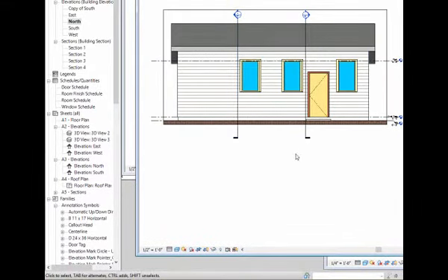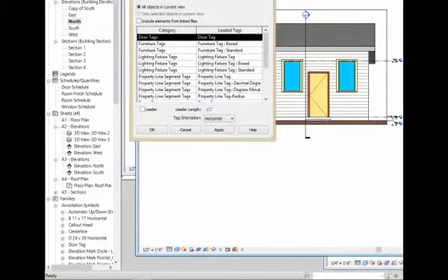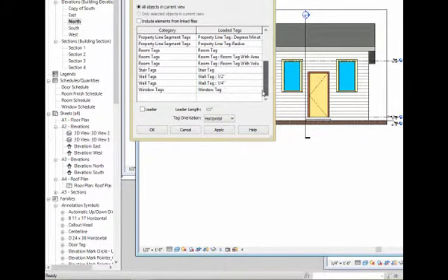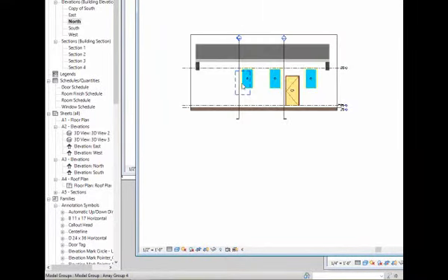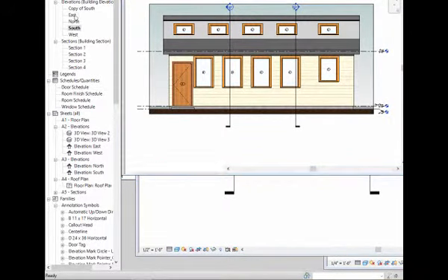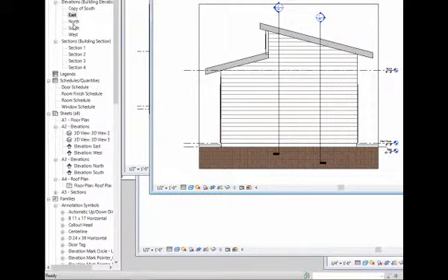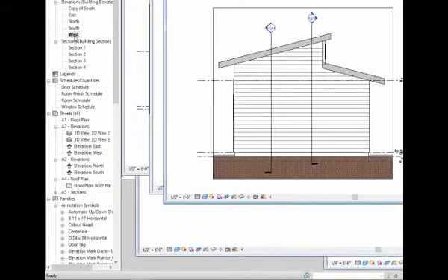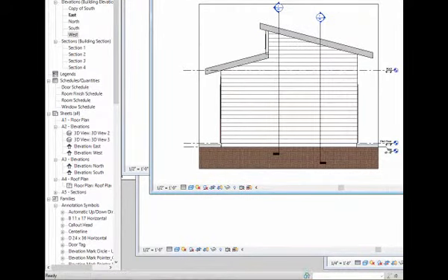Okay, here are those windows. In the same sense, I'd like to know what those doors and windows refer to in the schedule. What I can say is Tag All, and I'll choose the doors and the windows. And say apply, and it'll really quickly put all the different tags on for me. So that just saves you lots of time. His east doesn't have any windows or doors. His west, not there either. Okay, so we have all the doors and windows tagged.